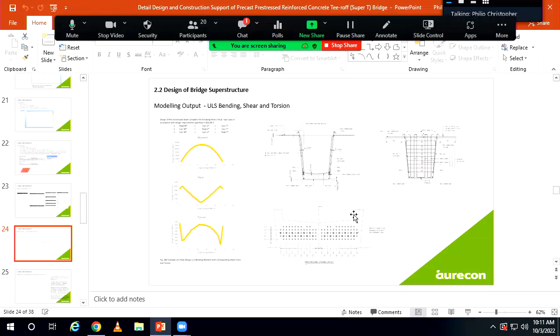But when you are just given a point A and a point B and told to link them together, this is when you try to use your imagination with Super Ts or the span types and play with the most effective options. Because you also have to understand that a lot of construction teams are familiar with the delivery and installation of Super Ts, but when it comes to cable stayed bridges, you're talking about specialized teams, international support, proprietary products, and special maintenance strategy. So that's a different type of complexity.